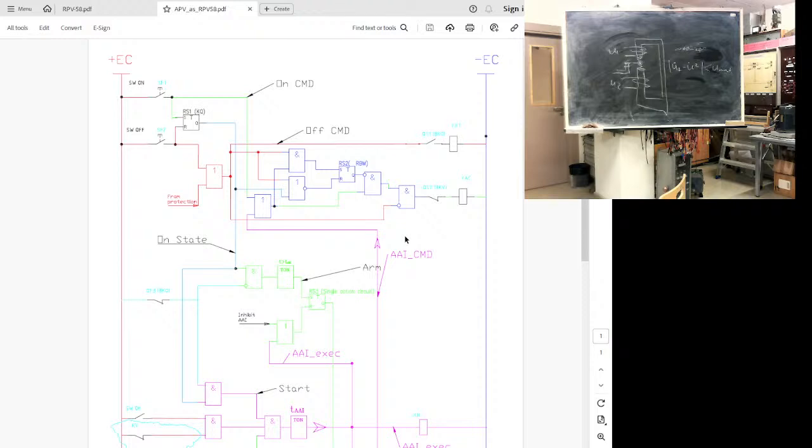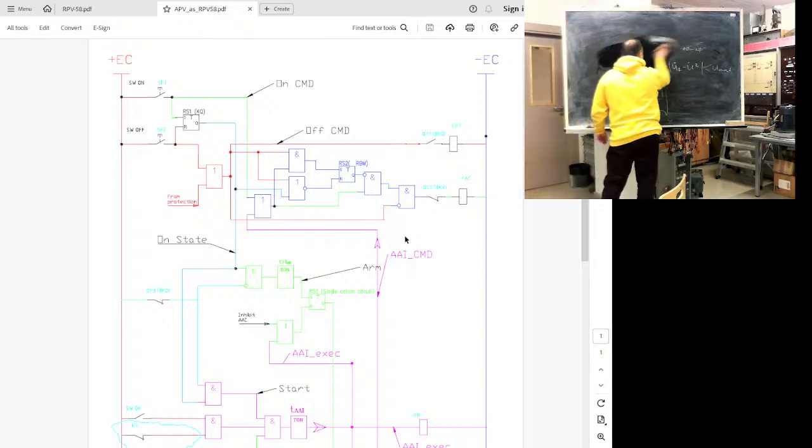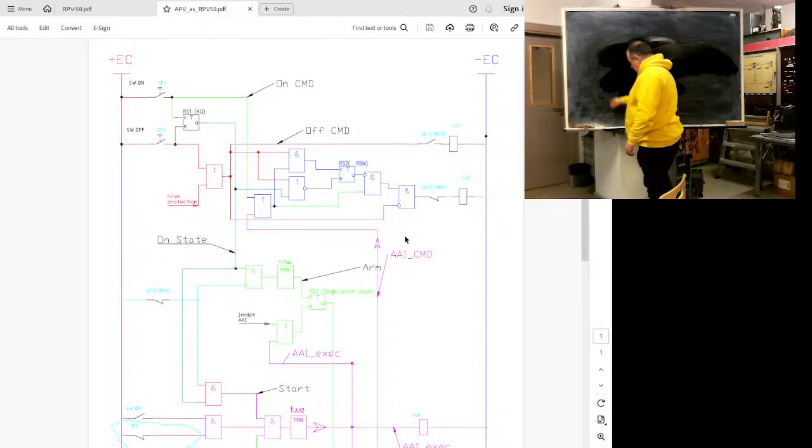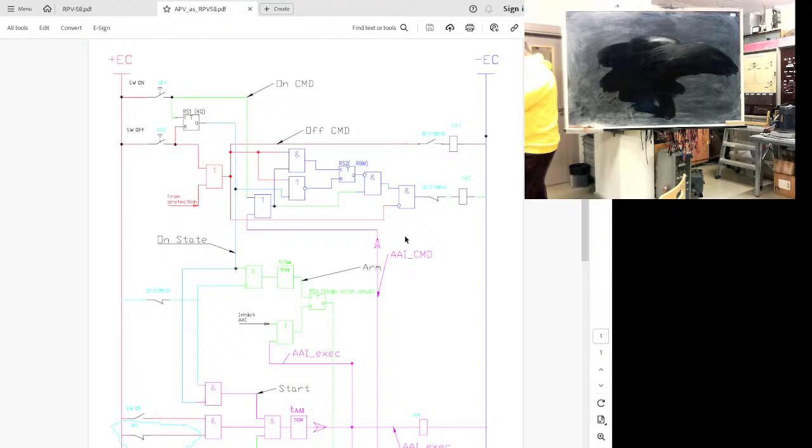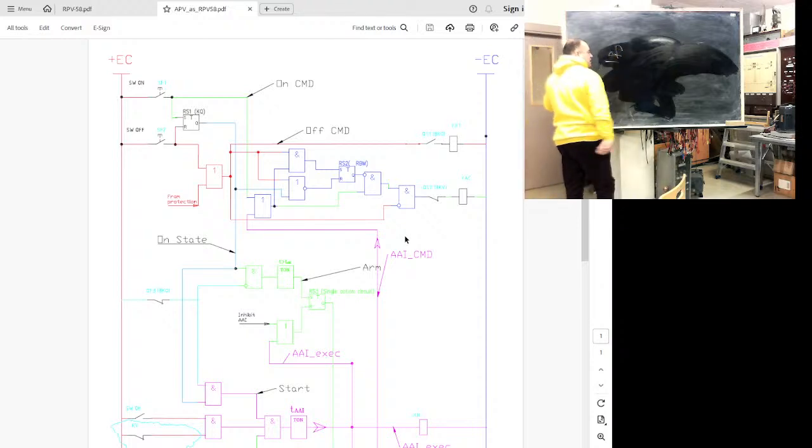Simple, very simple. It checks for synchronicity, but it's not enough. It's okay for a simple line where a difference in angle is nearly impossible. For a line of serious importance, this will not work. Why does it not work? Because this relay does not ensure what? A check for frequency difference.